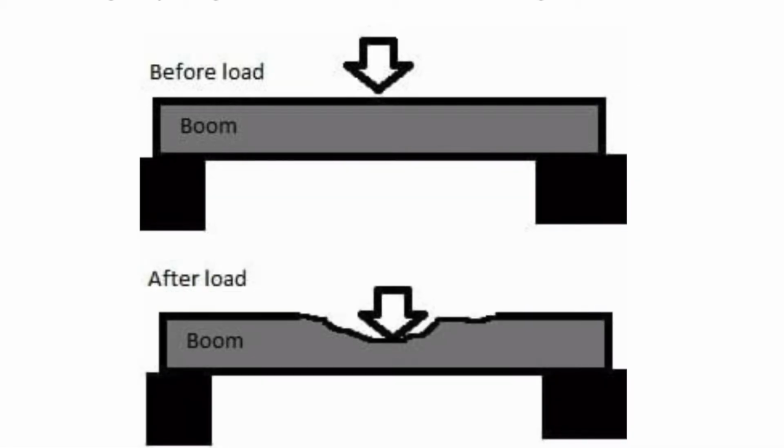The second type of failure is a shear failure. A shear failure can be imagined as a cutting failure. When the load is so large, it can physically crush or cut the beam in half. This is the worst kind of failure to have because it doesn't give any warning before it breaks. It just happens. As opposed to the bending failure, which creates a curve, which can tell people that the bridge could and potentially might break in the future.